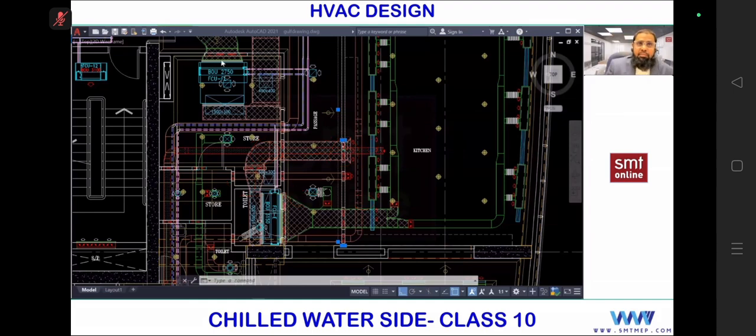Case 3 you can write AHU with supply plus return and fresh air duct. So in this case, for the supply side, same as above. Supply means supply duct, fitting, accessories, A terminal, same as above. First point for supply duct same as above. Now we have return and fresh air. So in this case what we'll do, we'll consider the longest between the two. So next point you can write between return and fresh air duct, consider the longest between the two.